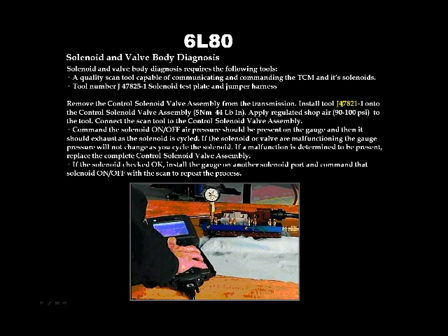That tool comes from Kent Moore. So if you were to dial up 1-800-GM-TOOLS, you'd get a hold of Kent Moore Tool, and you said, I want a J47821, they're going to send you what you're seeing here on the screen. That is going to be this whole plate assembly here in blue with the pressure gauge hooked to it. You also get this harness right here. So that harness that I'm highlighting in yellow right now is in fact provided with the kit itself.